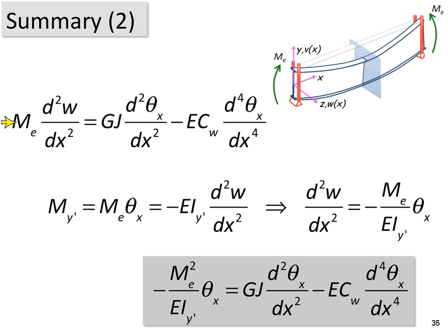So this is where we were from the previous slide. Now, 2 or 3 slides ago, we had an expression for the minor axis bending as a function of that applied moment me. And that slide showed us that me theta about the x-axis is what my prime is. But this my prime is also equal to, based on our moment curvature relationship, EIy times the second derivative of the deflected shape in the z direction. So from that moment curvature relationship and the resolution of moments that we did, we can solve for this second derivative, and it is equal to me over EI times theta x.